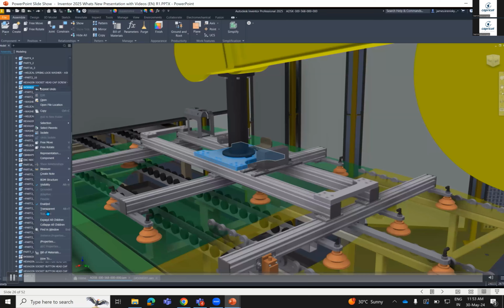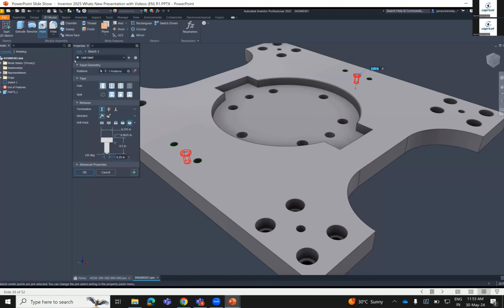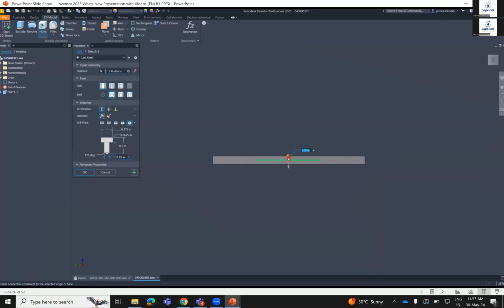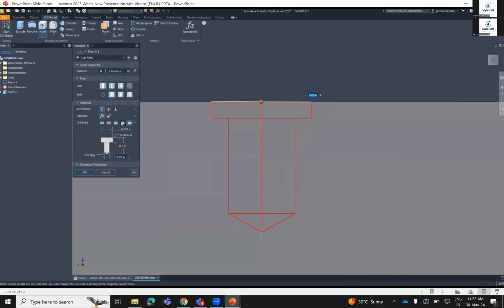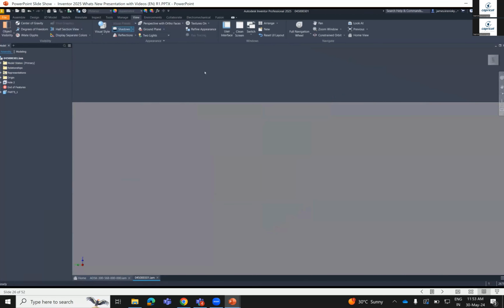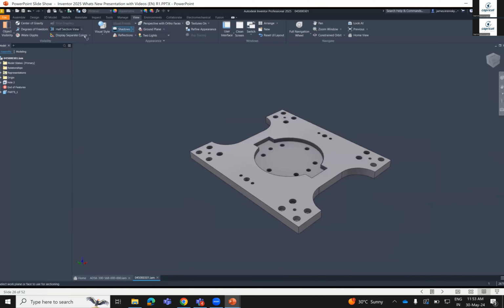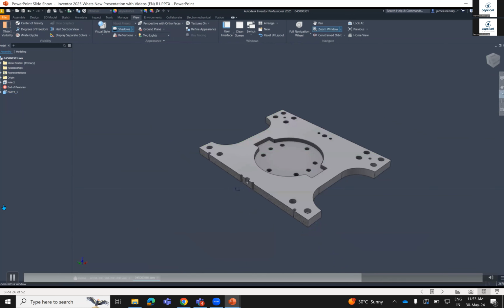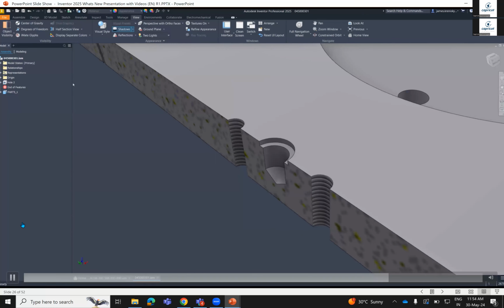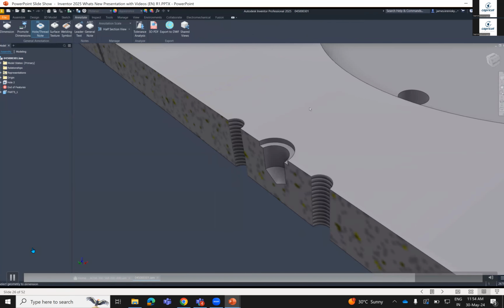Hole creation capabilities in Inventor now incorporate the ISO 15786 standard, which includes new drill point operations such as flat, angle V, and angle Y. This allows users to design holes in strict compliance with this international standard, highlighting our dedication to aligning with the latest industry standards and serving the dynamic needs of the design community. Additionally, we provide users with the flexibility to modify and create custom holes tailored to specific machinery or tooling requirements, ensuring adaptability to a wide range of design scenarios.